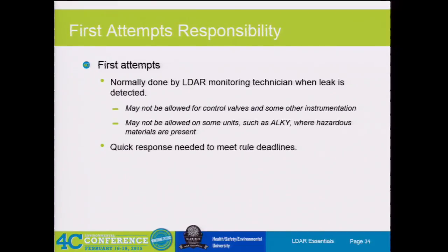I don't know, so would it be out of service? But it's not running. So you can still sniff it then. Do you have process fluid in it? That's a really easy one then, because it's not really running. Our approach is, it is what it is. A pump that's not running can leak just like a pump that's running. So whatever state it's in, is how we monitor it.